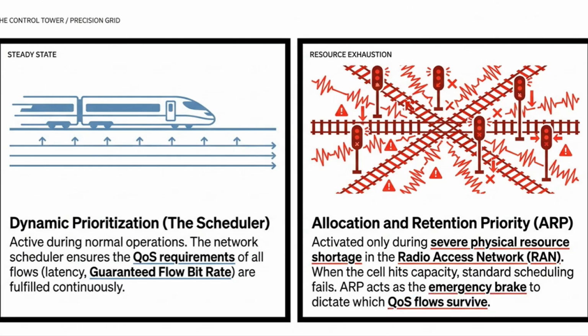When that network load hits its peak, how does the system choose who gets to talk and who has to wait? Well, across the end-to-end quality of service path, we have to remember that not all communications carry the same urgency. I mean, an automated train control signal is objectively more critical than a routine data log from a maintenance sensor. Because of this, we need a highly dynamic prioritization framework. This framework is what ensures that our absolute most critical railway operations always get precedence when bandwidth gets tight. It's how we enforce that strict quality of service to guarantee congestion-free communication when it matters most.